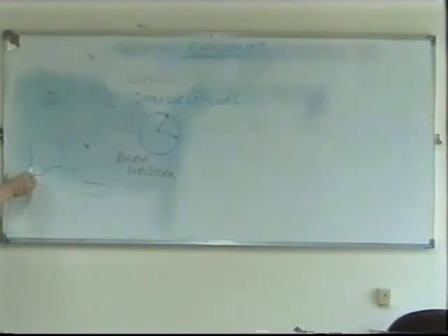for more convenience. But whenever you radiate electromagnetic energy, if you have any metal close to the antenna, it's going to change the propagation of that antenna. In other words, although the antenna itself radiates in all directions, when it hits the car, you're going to get a little bit of reflection. And this is going to change the pattern a little bit.